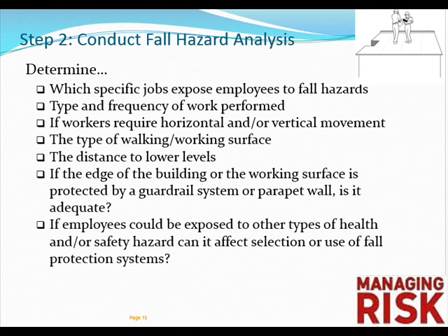Step 2. Conduct fall hazard analysis. Determine which specific jobs expose employees to fall hazards. Consider the type and frequency of the work performed, if workers require horizontal or vertical movement, the type of working surface, and the distance to lower levels.